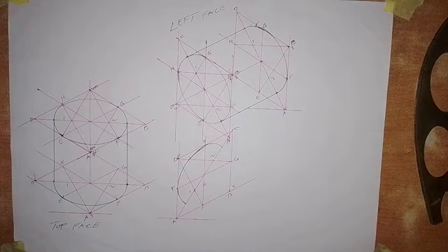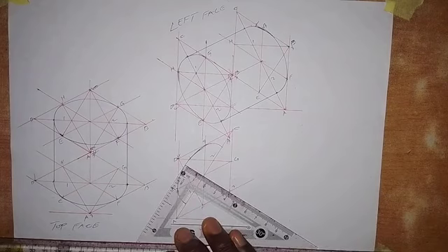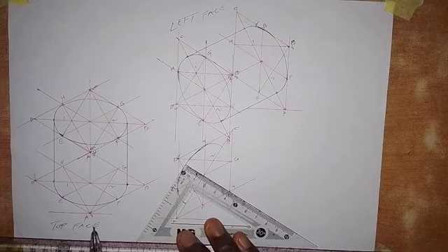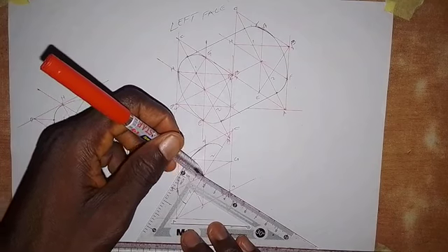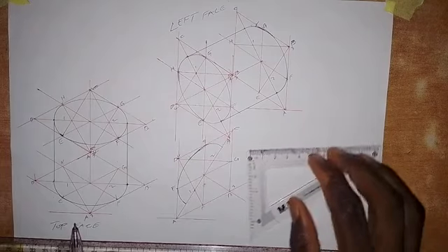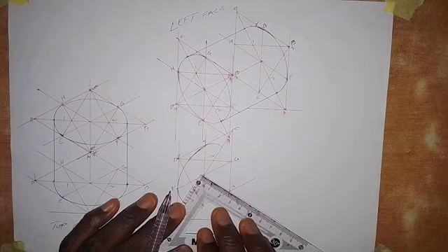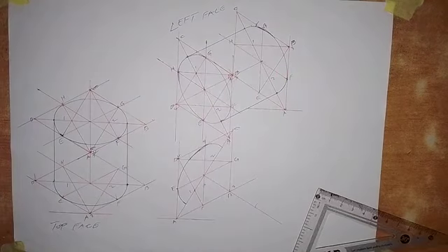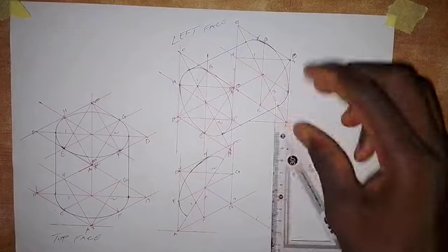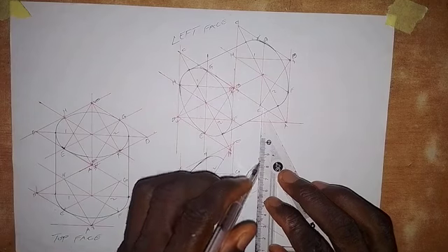half of the circle. So the next thing that we are going to do is to draw, so come to this center, okay, to the midpoint here. So draw a line in this direction like this. And then from this center, take a measurement of 50 millimeters. So here we have 50. So with this 50 that we have here, we are going to draw a vertical line through this point, like this.